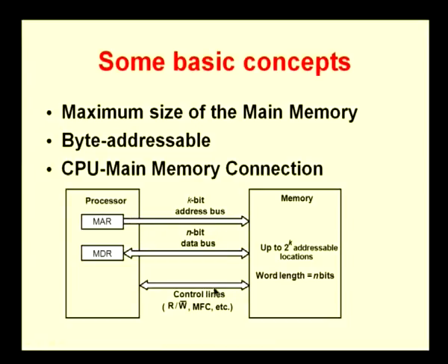And then we will have control lines, a read/write control line, and maybe you may also have a control line which comes back as feedback from the memory when an operation is completed. So, this is typically what you will have in terms of the interface between a processor and a memory. When we talk of any memory device, therefore, we need to understand how the addresses will be specified, how the data at that particular address will be obtained, and what the control lines are that need to be specified for that. When we talk of memory again, there are certain terms that we normally refer to.